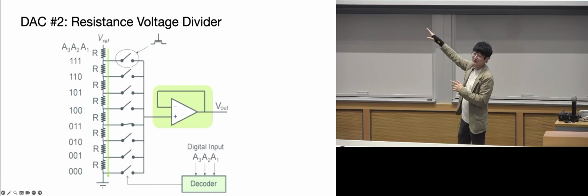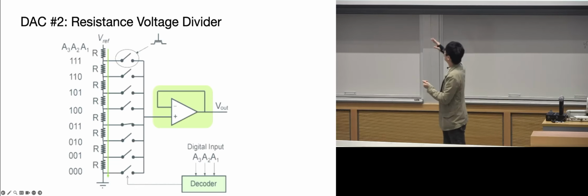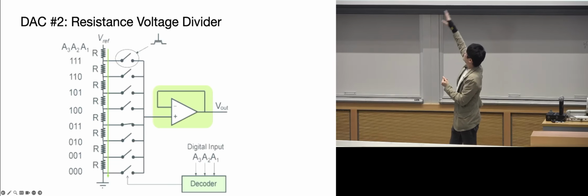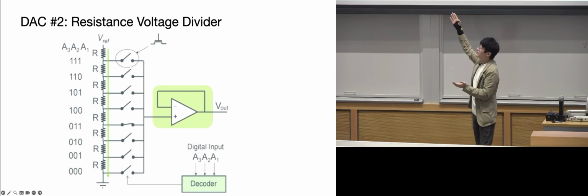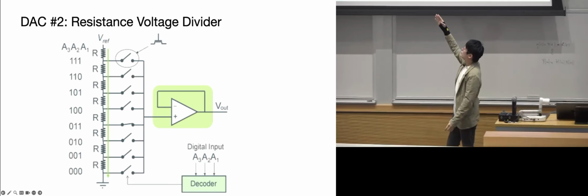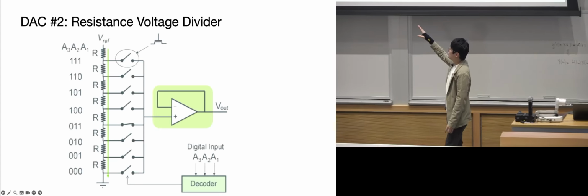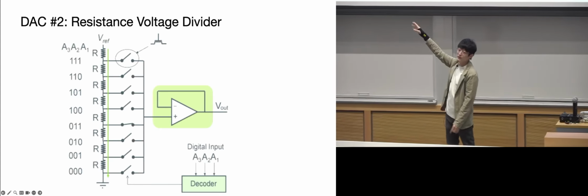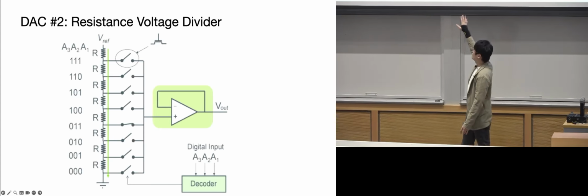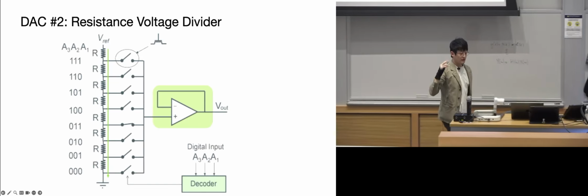It's not going to be these, but just as an indicator of the switch, and then that will just go through a voltage follower circuit to be used as Vout. And typically, we will use a decoder to control the input for all these switches. So you only need 3 bits to control this entire piece of hardware.